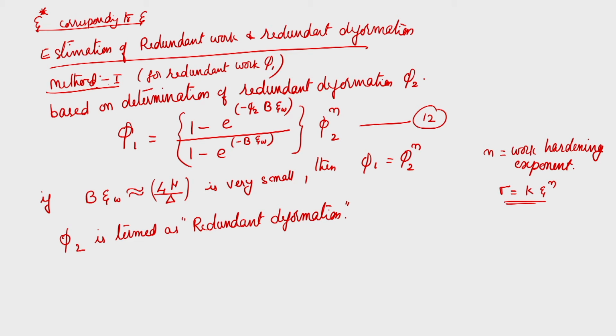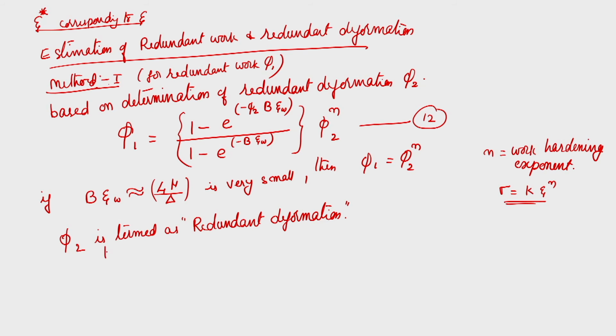If you refer back to that lecture, maybe the second or third lecture, I am not sure, on the basic fundamentals of plastic deformation, where the effect of die angle and other things came up, you will find that redundant deformation is defined, and I have clearly mentioned how to determine that epsilon star. Okay. And this is the measure of extra deformation or equivalent strain.